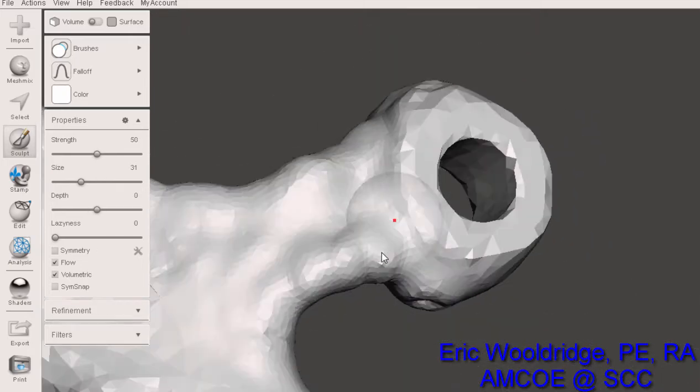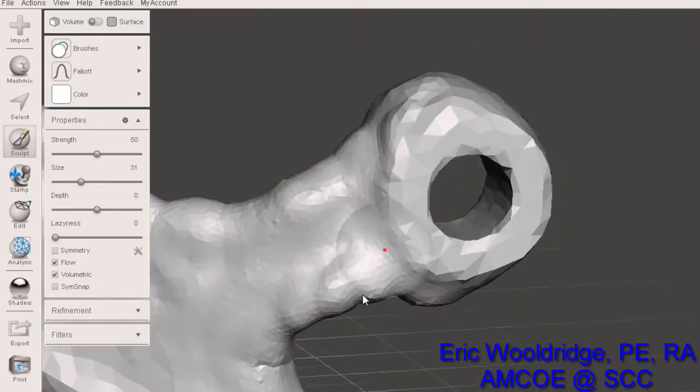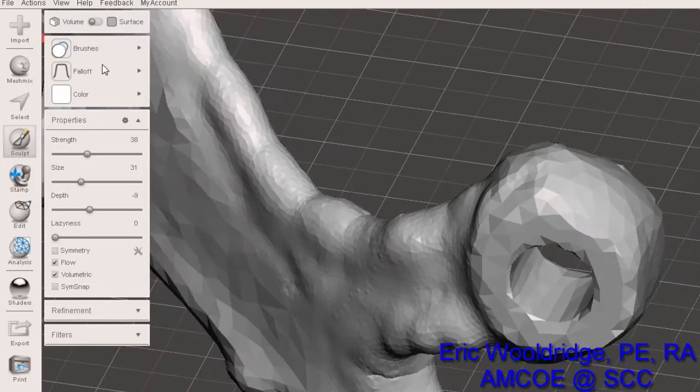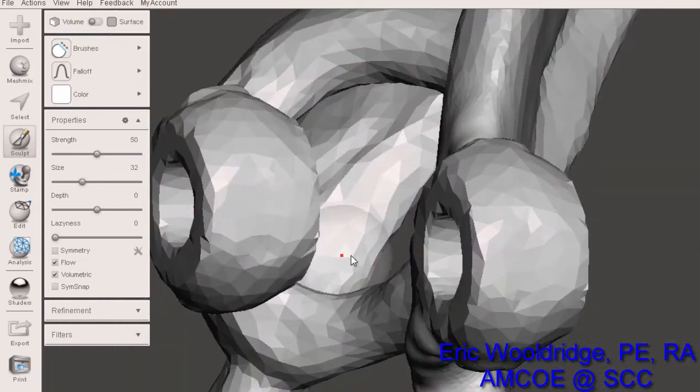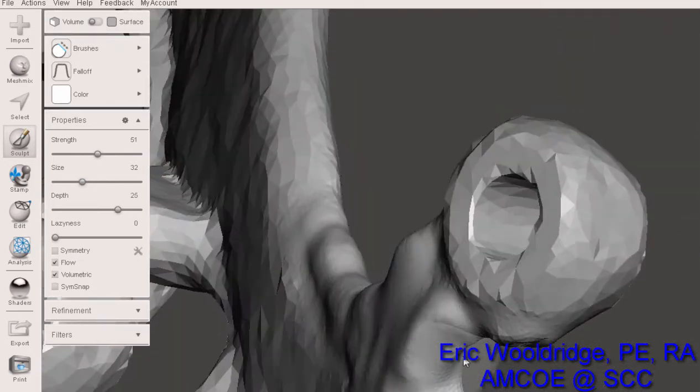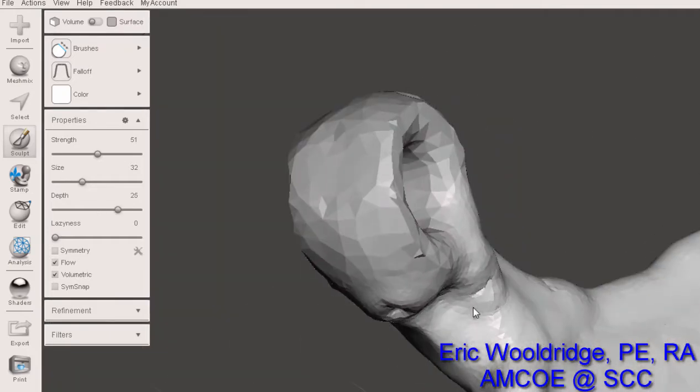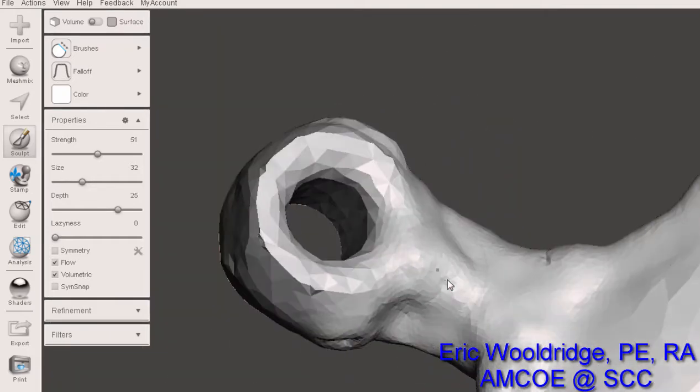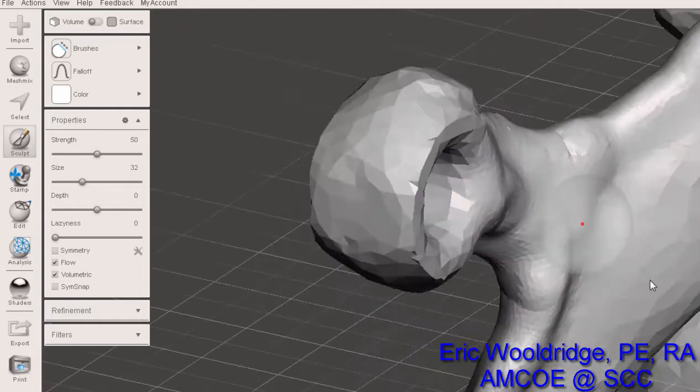So I've thickened it up, as you see right there, and now I'm going to turn around and use some of my smoothing options, such as my flatten, to flatten it back down a little bit, get rid of that bubble effect, and maybe smooth it back out. Those bubbles fill material up pretty fast for us, which is nice, but it doesn't always necessarily result in that major of a benefit, and sometimes those bubbles can be so extreme that support material might want to pop up because of those bubbles. So I'm going to smooth it out just a little bit.